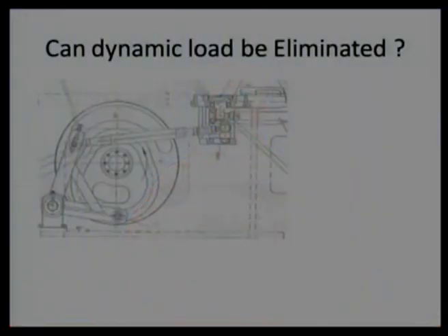That can also be done, we can argue on that. We can go for a better design, we can go for complete dynamic design, multi-body dynamics can be used. But the question comes, will that be a 100% solution for us? So, this slide poses a question: can dynamic load be eliminated? To answer this question, it is always preferable to see how the cam follower mechanism is really functioning. What is the interaction between cam and follower?